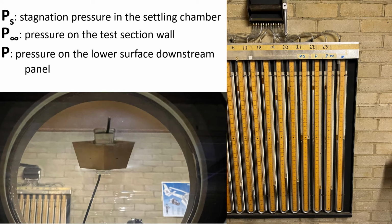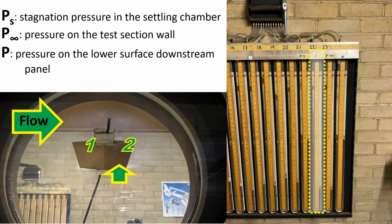And also we have P, which is the manometer number 22, and that's the pressure on the lower surface downstream panel. And here is showing a close-up view taken from the lower side of the airfoil. You can see there are two pressure taps. One is on the leading edge, the other is on the trailing edge, both on the lower surface. And actually we are taking the measurement on pressure tap number 2, which is P.